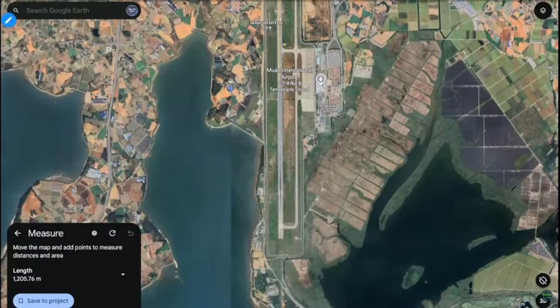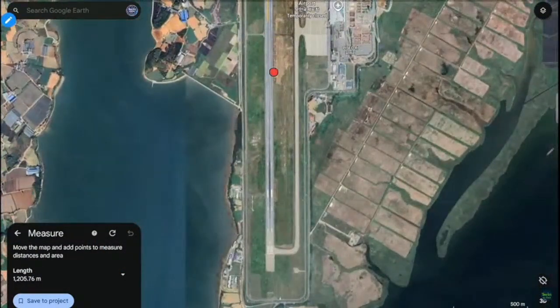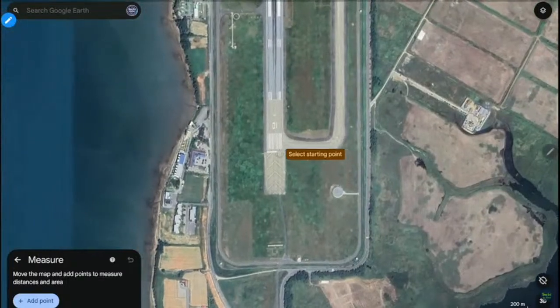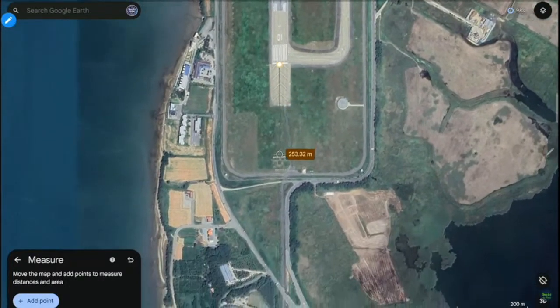But here, that ground effect kept the plane from touching down sooner. So by the time it touched down, over 1,000 meters of the runway was already consumed, leaving not much left for actually coming to a stop. Now, the landing gear was not extended, which is something that we'll get back to here in a second. But as you can see here at this airport, once you've cleared the threshold, you have about 250 meters from the end of the runway here to this embankment. And that is a requirement, and that was met.